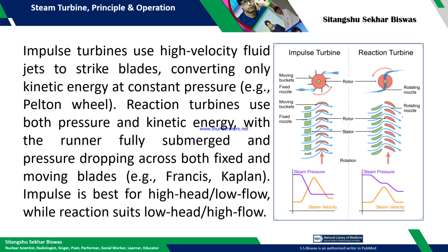If you want to categorize the turbines, those are basically of two types. One is impulse turbine, another is reaction turbine. As the name suggests, in case of impulse turbine, the torque produced in the rotor shaft is due to impulsive force, and in the reaction turbine, the rotation of the turbine is taking place due to reactive force. With one simple example you can understand what is impulsive force and what is reactive force.